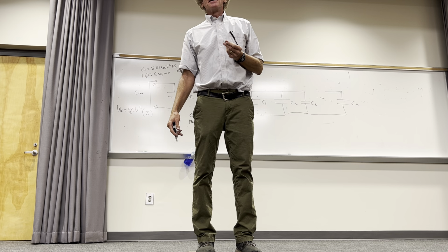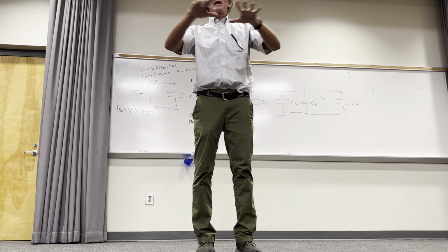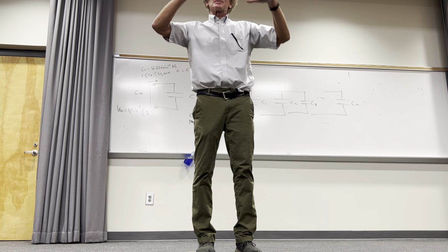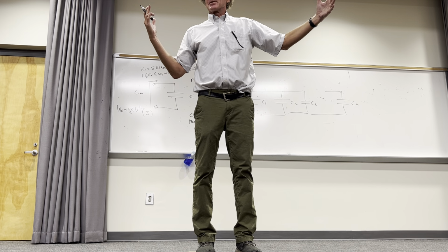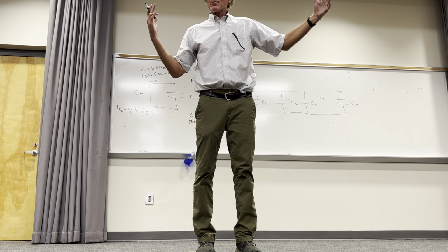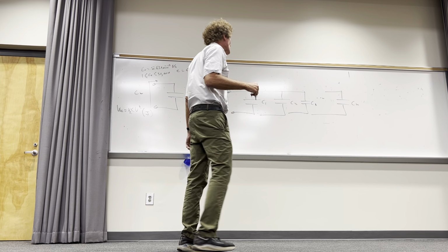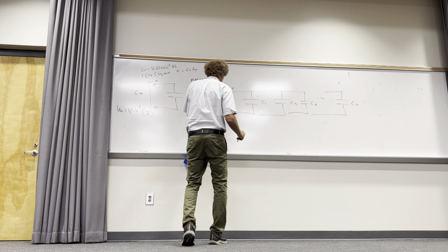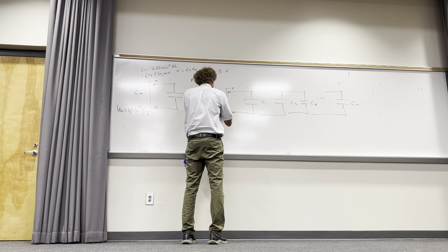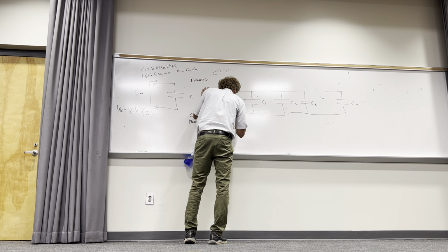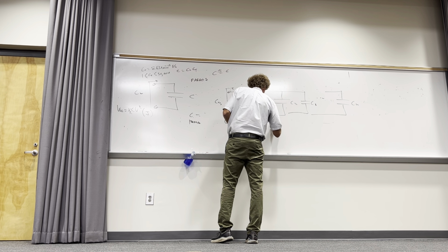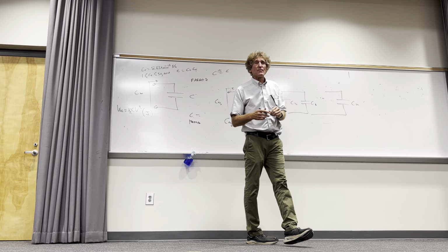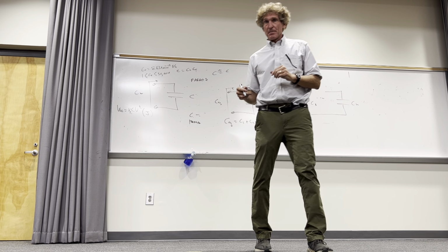Gut feel, think. Capacitance is proportional to the area of the plates. What do you think happens to the area of the plates if they're effectively added? It just increases, right? The distance doesn't change. You add them as if they were in series. For the total capacitance here, C equivalent is just equal to C1 plus C2 plus dot, dot, dot, plus Cn. It's just the sum of all of them in parallel. Can you all see that? How many can?